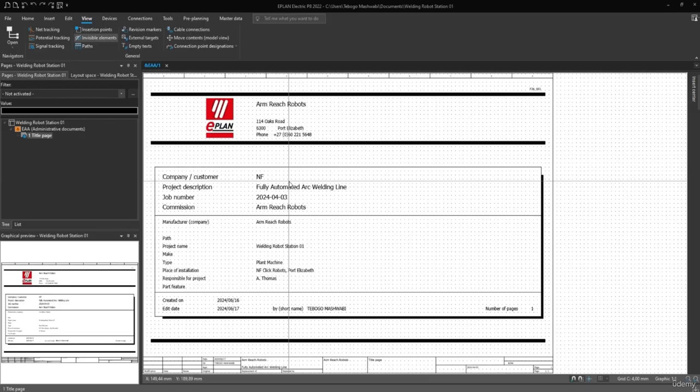The sixth one is user-defined structure, which is normally a hashtag sign, but it can be changed. When you change it, it shouldn't cause conflict, which means that you can't change it so that it becomes a double equal sign or an equal sign. You can't change it so that it becomes a double plus sign or a single plus sign, because those are already taken by other structure identifiers. You also get the 7th structure identifier, which is the higher level functional number. This is mostly used in fluid drawings.